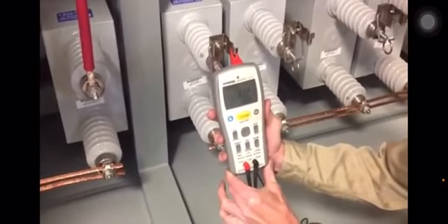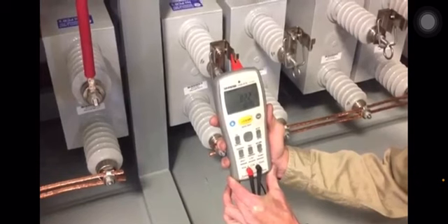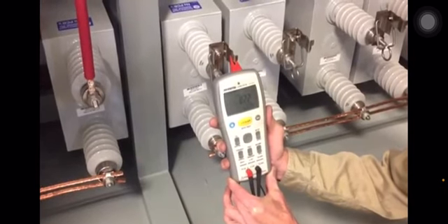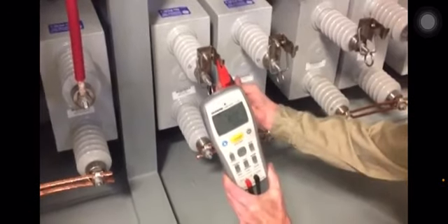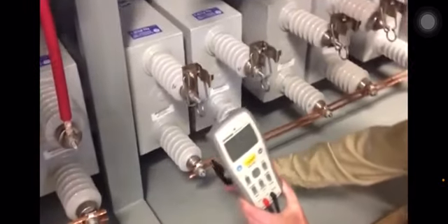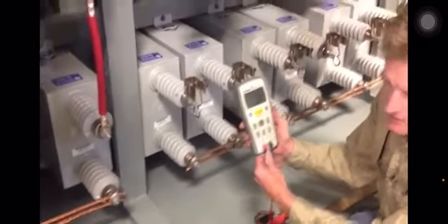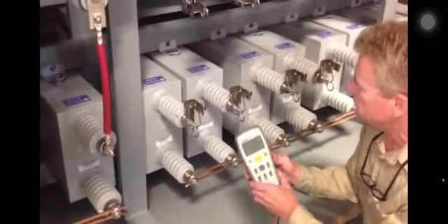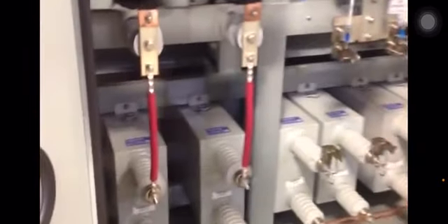And in this case, we're measuring 82.2 microfarads. So what does that mean? Well, that's the measured value, and in order to assess whether or not that's correct, you need to go to the information plate on the capacitor itself, and that could be at different locations depending on the brand of capacitor.